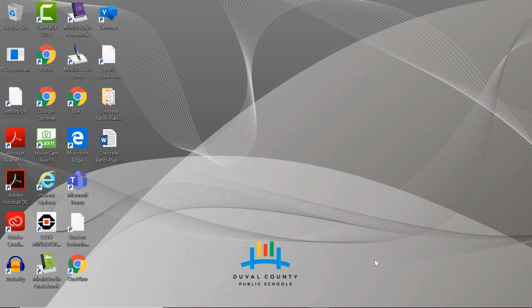E. Specific gravity, unit weight, absolute volume, yield. 1. When talking about specific gravity, everything is compared to water. Water is considered to have a specific gravity of 1 and has a unit weight of 62.4 pounds per cubic foot. If something has a specific gravity greater than 1, it is more dense, weighs more per cubic foot than water.